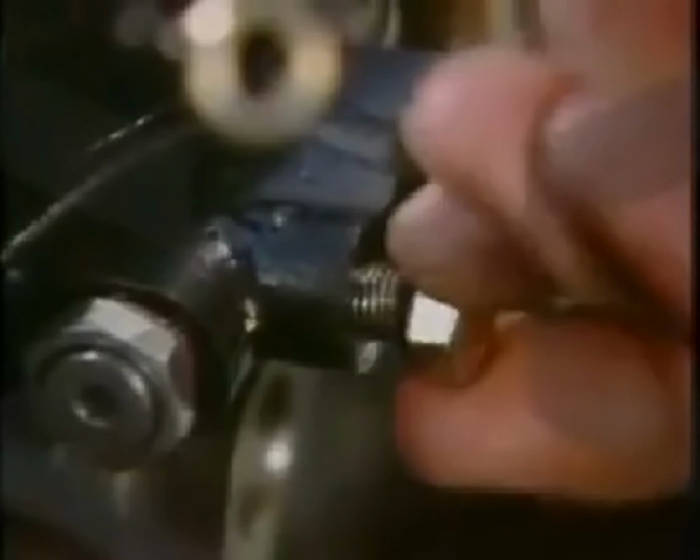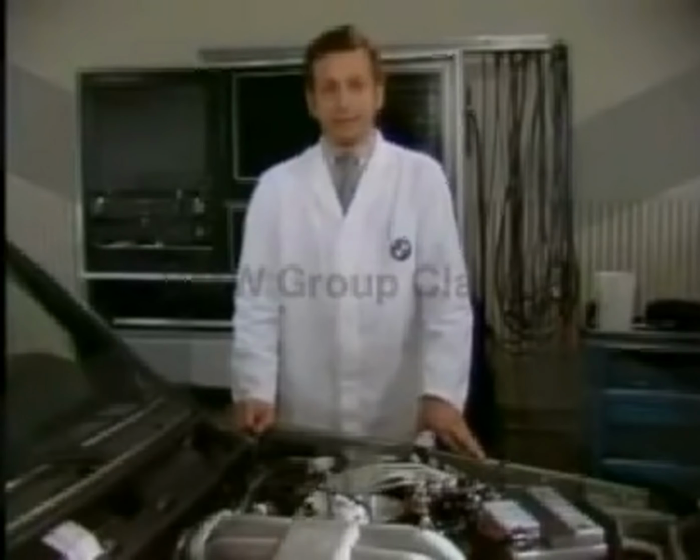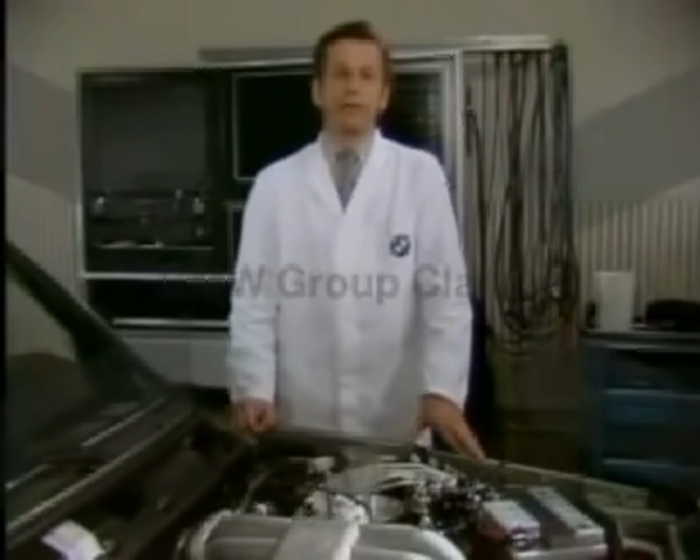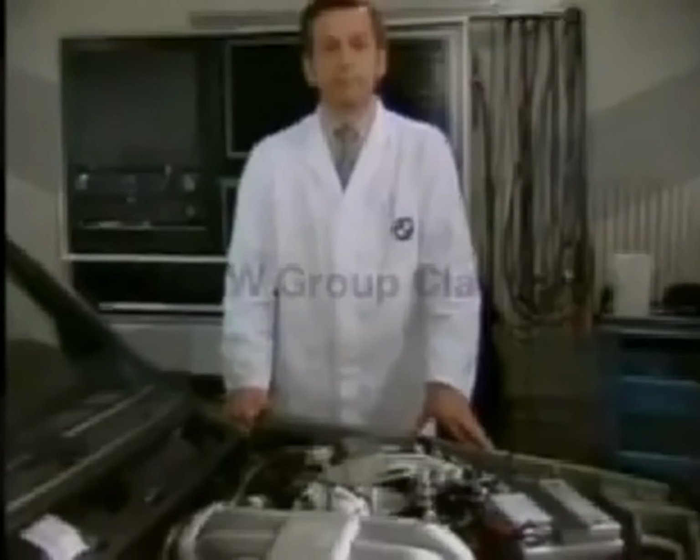We remove the return pipe from the warm-up regulator at the fuel distributor, plug the opening, and again test the pressure. If the pressure reading is still outside the tolerance limits, then the warm-up regulator is defective and must be exchanged. If it is not defective, we check the non-return valve in the fuel distributor, then the return pipe for blockage.